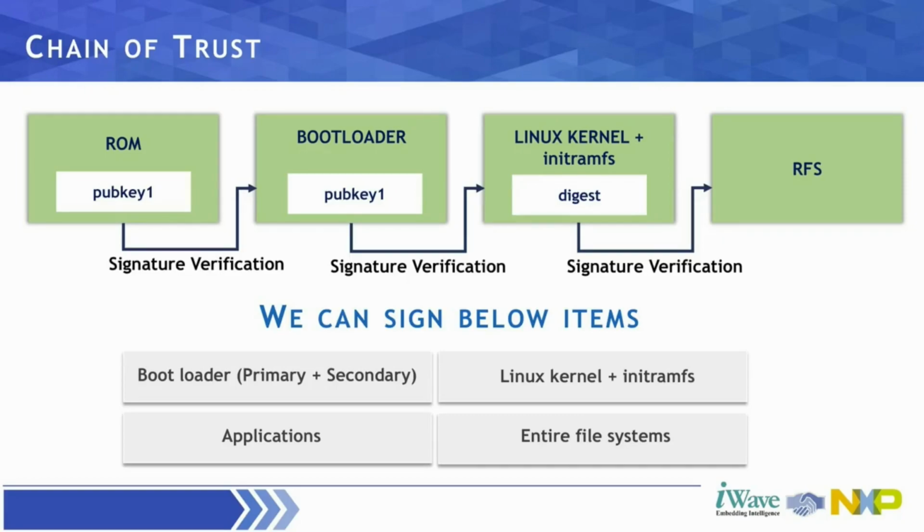And to make it very reliable, a hardware implementation is what is most trusted upon, which is immune to hardware and malware attacks. Through the use of signing and trusted elements, secure boot establishes a chain of trust which boots the system securely and validates the integrity of the software. Once the initial bootloader is authenticated and executed, the chain of trust can be continued by authenticating each of the next loaded images before executing it.